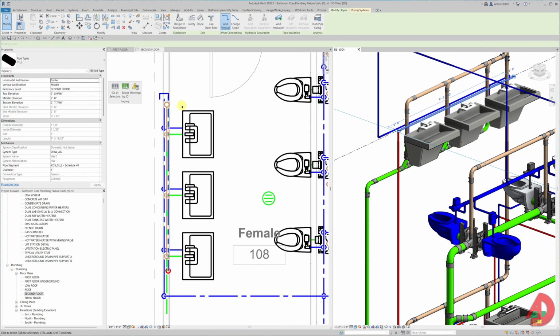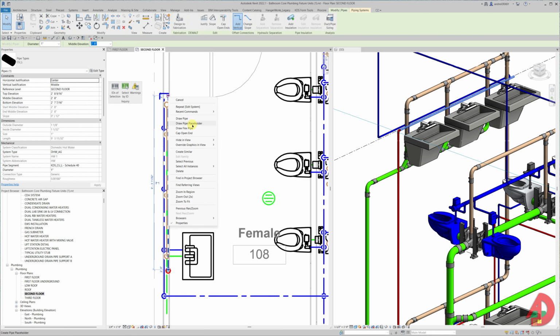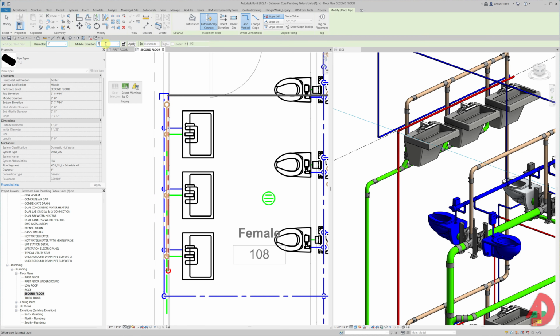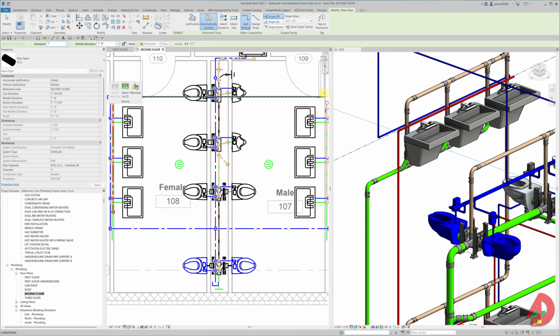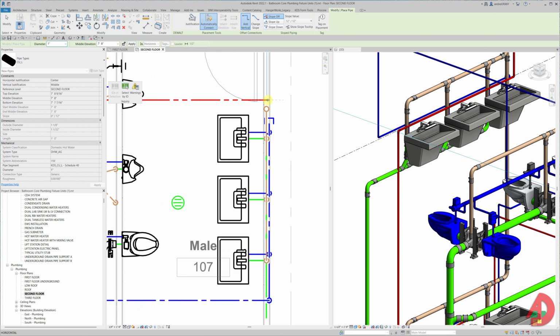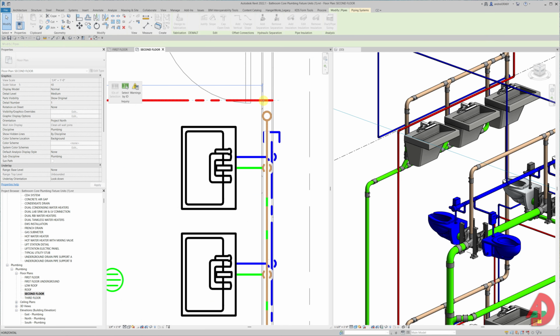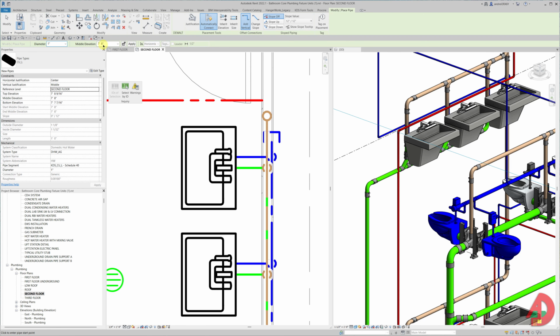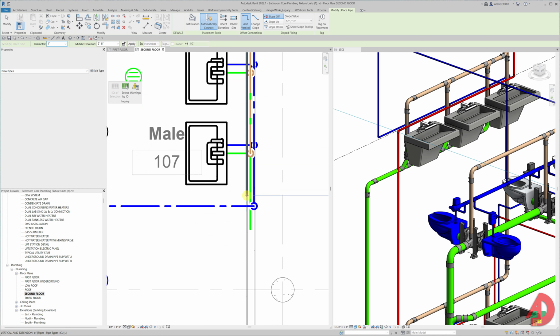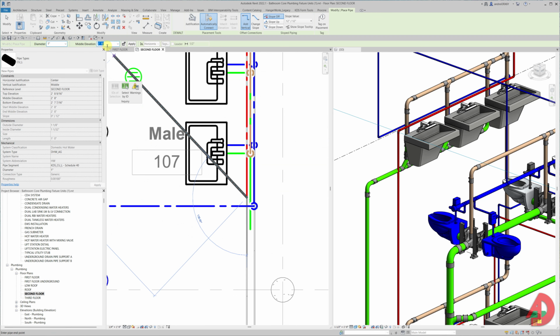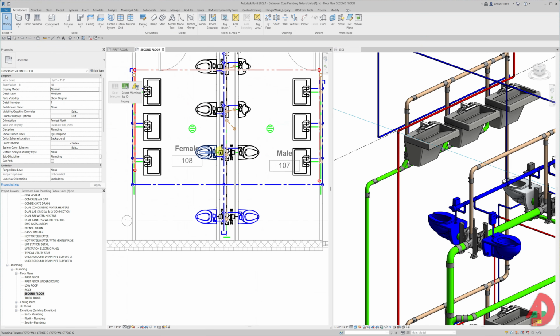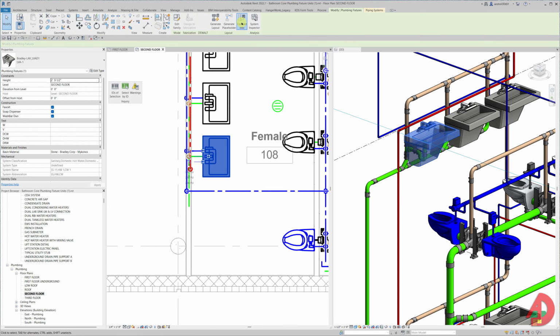Back again to second floor plan view, I will continue the loop to 7'8" elevation and run across to the right. I will drop down in the wall with 2'8" elevation, click once and then set the elevation to -6 to drop down to first floor. Next, I will connect all plumbing fixtures on second floor to my hot water system loop.